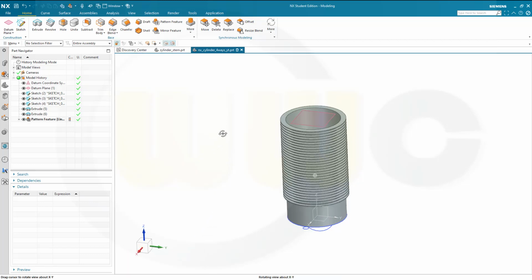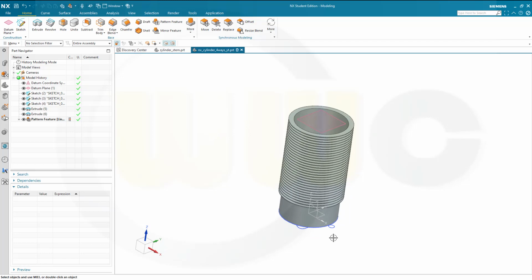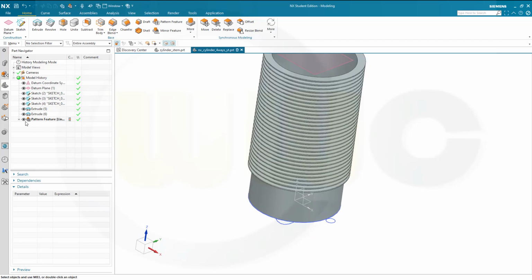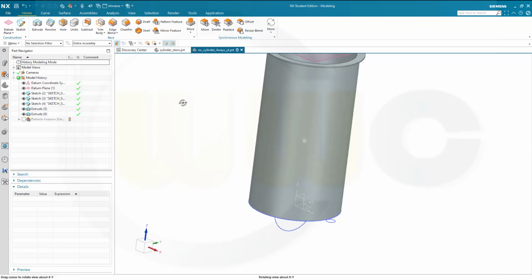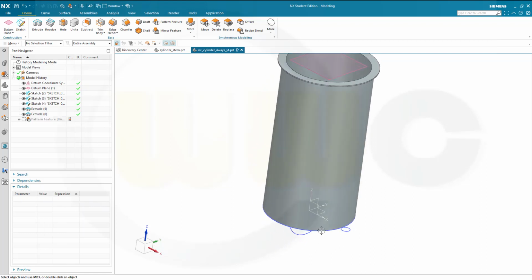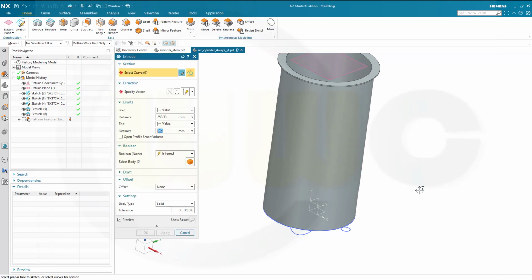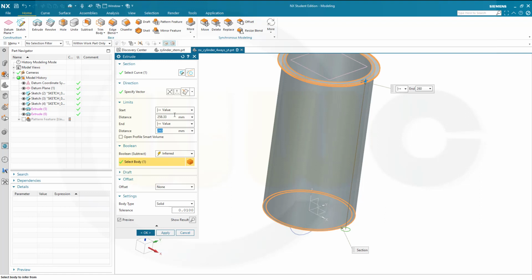Nice. Now, this one here should be an extrude. I would just, for the moment, suppress this feature so it's better visible. What will happen if I do that? It will not work. I go for an extrude, select this one here. Again, it's 260 minus the 1.67. That's wrong, so go for 260 minus 47. That would be the complete length of that flange.